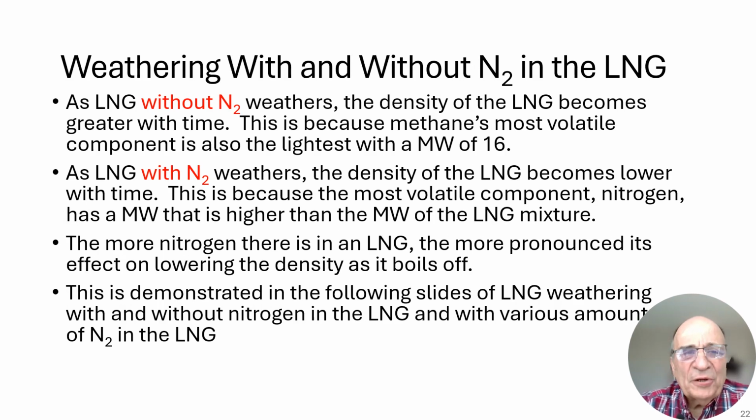This brings us to the point where we can discuss weathering, which is a boil off over a period of time with and without nitrogen in the LNG. Let's take a look first at how LNG without nitrogen weathers. What happens to its density? Its density becomes greater. And why?